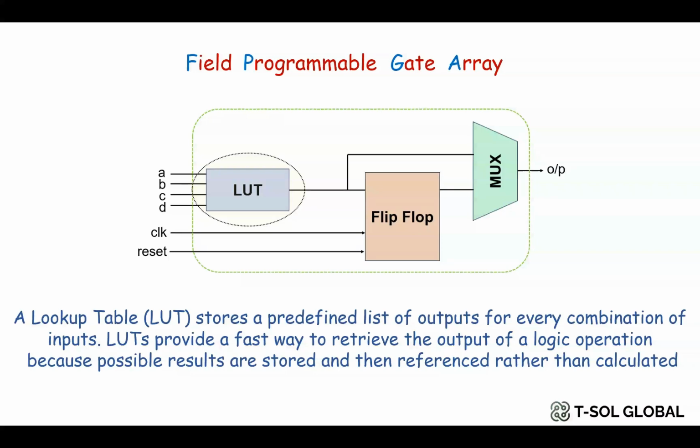The way FPGAs typically implement combinational logic is with LUTs. And when the FPGA gets configured using a language such as Verilog or VHDL, it just fills in the table output values, which are called the LUT mask, and is physically composed of SRAM bits. We'll try to cover how SRAM works in an FPGA in another video. Let us know in the comments section if you are interested to learn more about SRAMs.